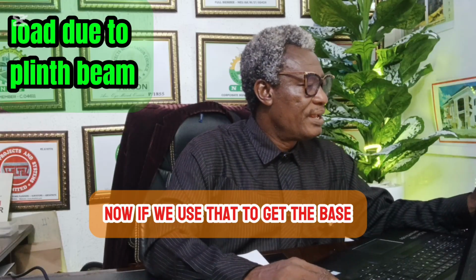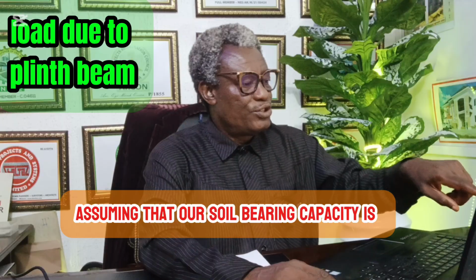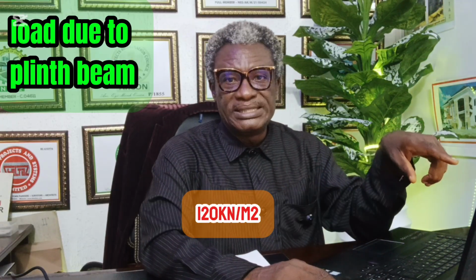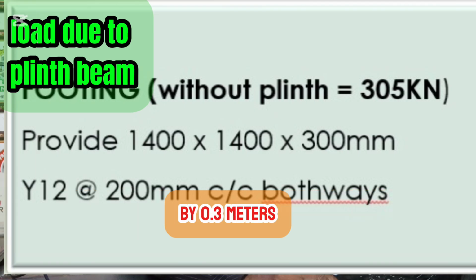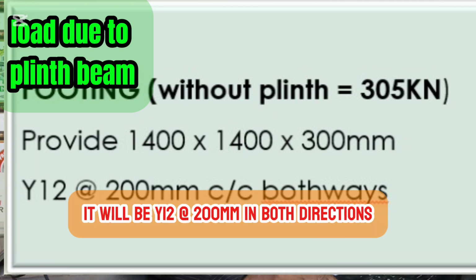Now, if we use that to calculate the base, assuming that our soil bearing capacity is 120 kilonewton per meter squared, our footing is going to be 1.4 meters by 1.4 meters by 0.3 meters. Then for reinforcement, it will be Y12 at 200 in both directions.